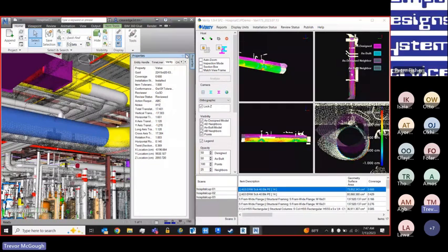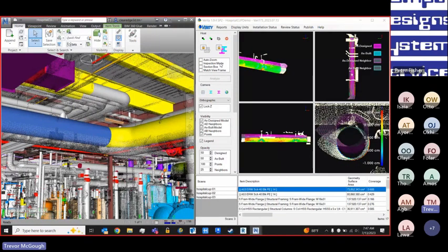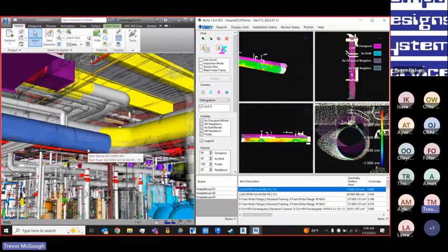And now we have the second key one, and that's going to be the button right here that looks like two I-beams. So if you watch the pipe over here on the left, at the click of a button, you can see it moves. So Verity will take and actually apply the as-built transform. So I can do this one at a time, or I can do it for, say, all the items in my analysis at once.